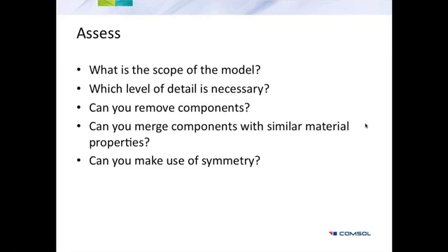Something that comes to mind is, of course, to model everything, because the more detail I include, the better my multiphysics simulation is going to get. Well, that is not necessarily true. Unfortunately, it's actually quite the opposite. If you include all your details in the simulation, a lot of times you might not be able to solve it because you would require quite a lot of computer resources.